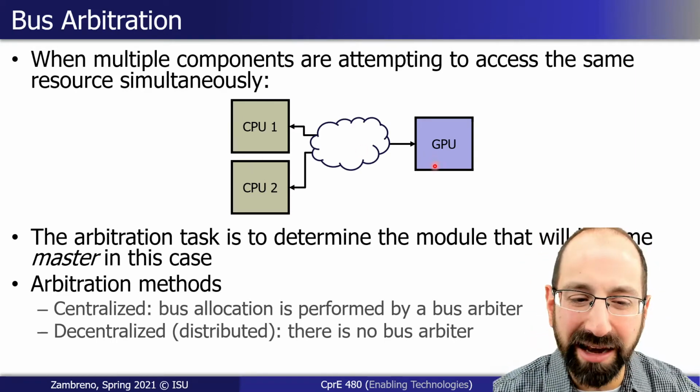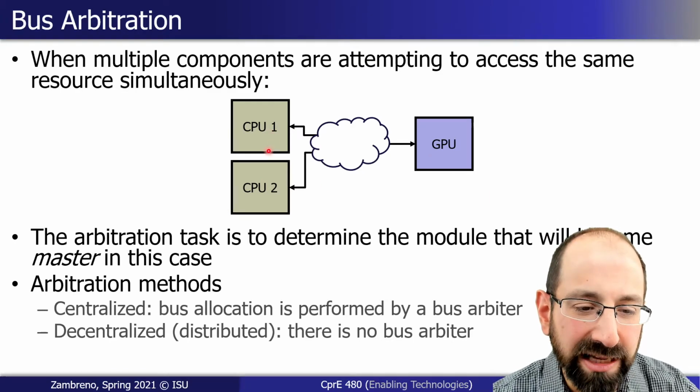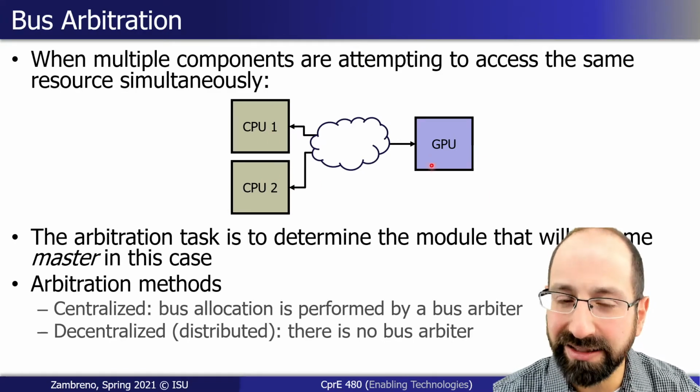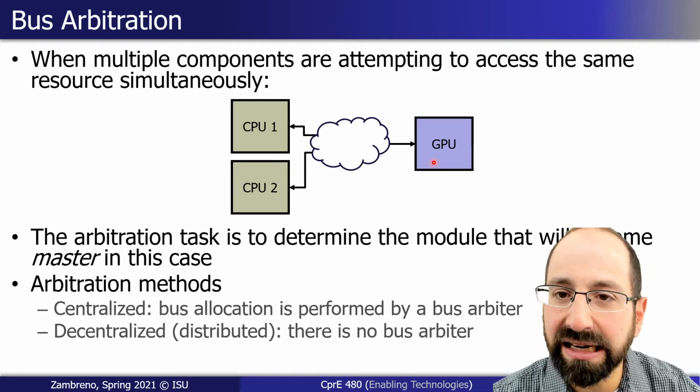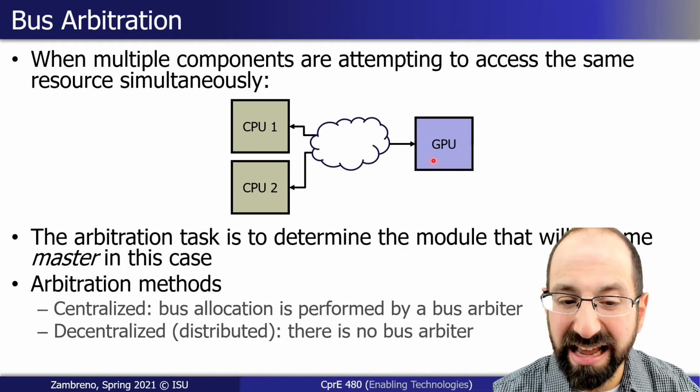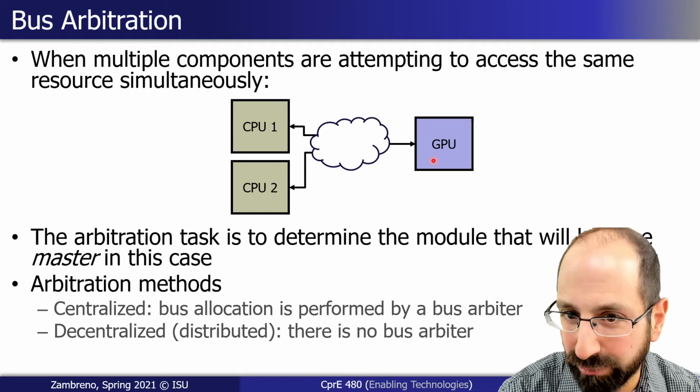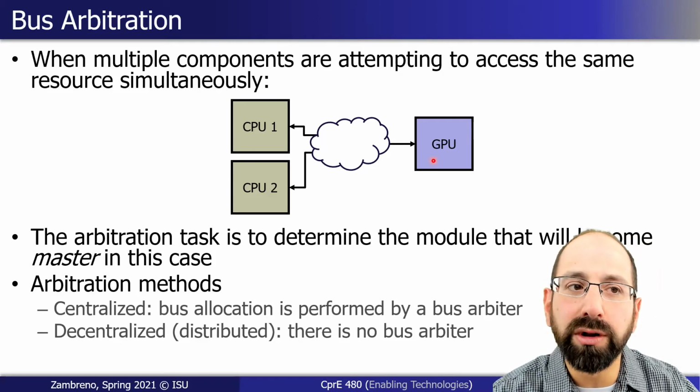It doesn't have to be that. It could be two IP cores that are mastered on an AXI bus trying to copy or read data or send data to a slave on that same AXI bus. It's the bus itself that is the shared resource in that case. And that's the role of an arbiter.